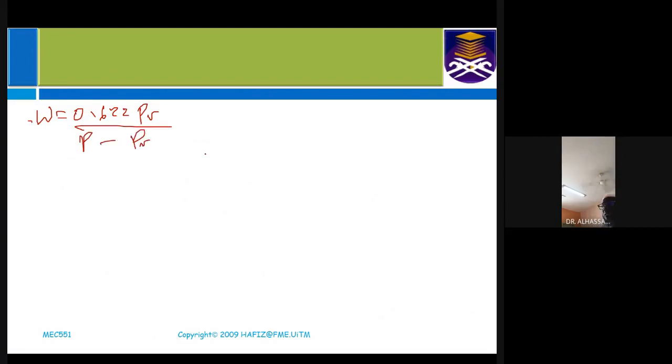So with this in mind, we will have 0.622 times PV, which is 2.38 kilopascal, all divided by 100 minus 2.38.